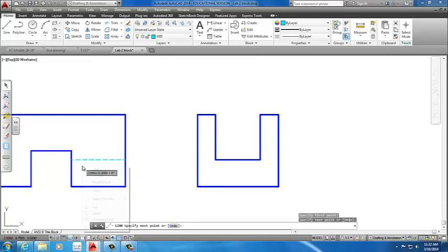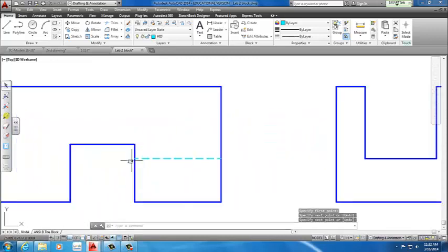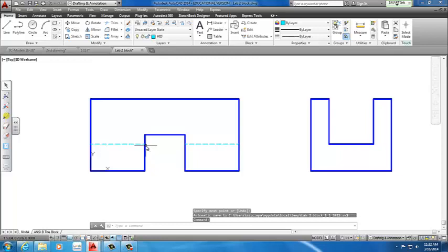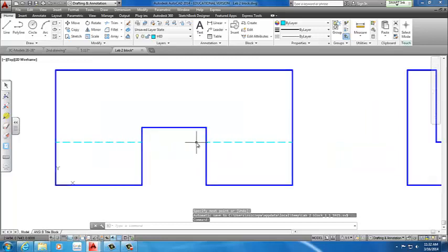Unless you don't have this on, it should work. It's going to ask you, do you want to convert lines to polylines? The default is yes, so you just click enter. We do the same thing on the other side, on the arcs, and follow through with it. Next part is you type in J for join. You want to join these polylines together, so we have those as one new line. They're still separate little pieces.